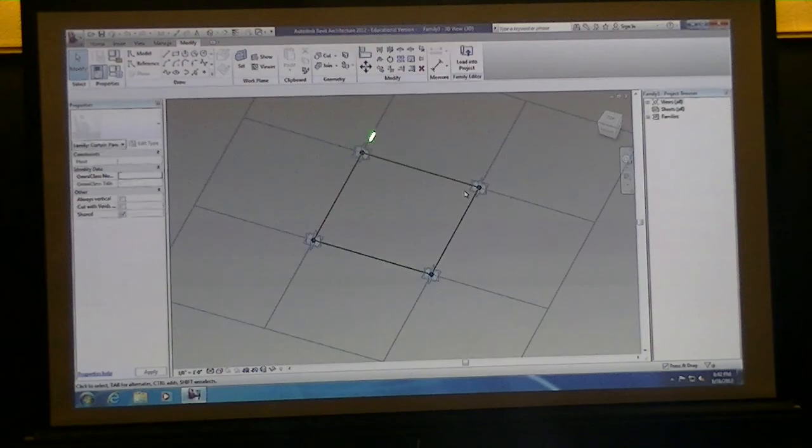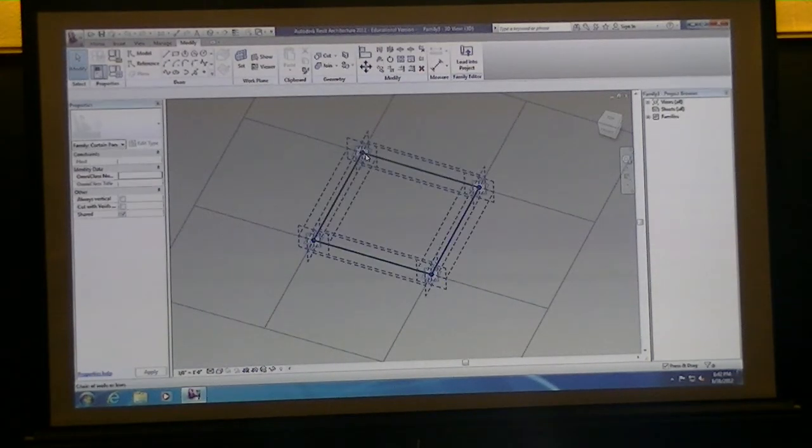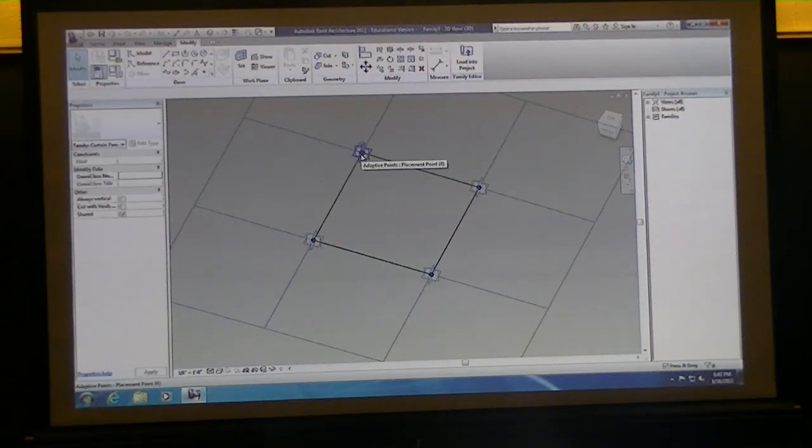The point of this is the corners of this grid are adaptive points that will stretch to the grid of a divided surface. So in this particular pattern, we're not going to be working with actual dimensions, but more like scalar percentages and so forth as we move forward.